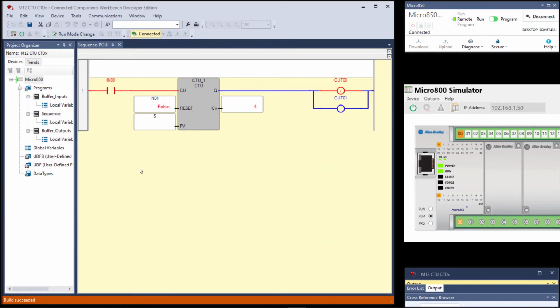If you want to count scans, just use an add instruction, unconditional. Adding 1 to a variable and saving it in the same name. In other words, you're just incrementing the variable by 1. Same thing with subtract, if you want to subtract scans. So that's what we were demonstrating in this part of the lab.